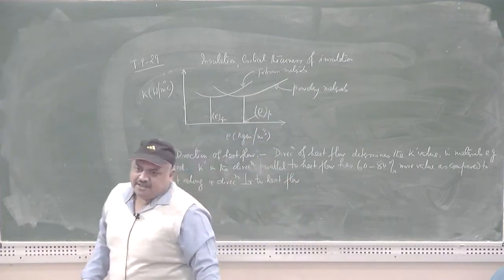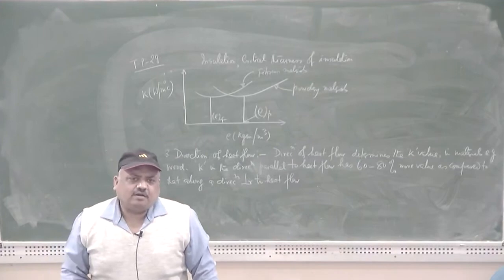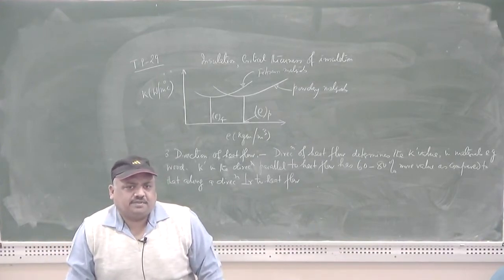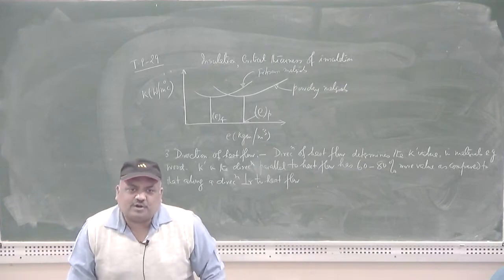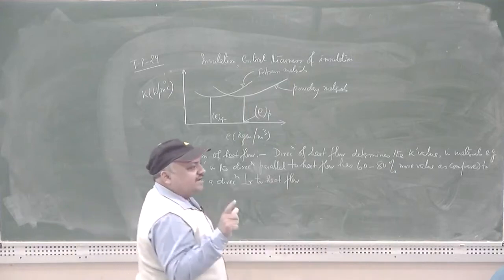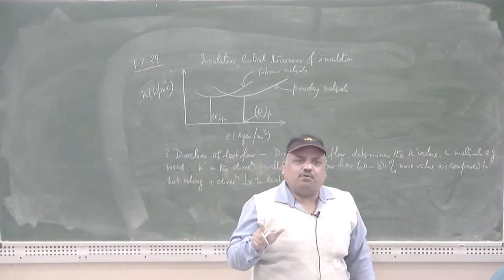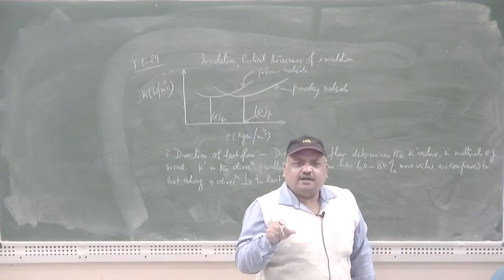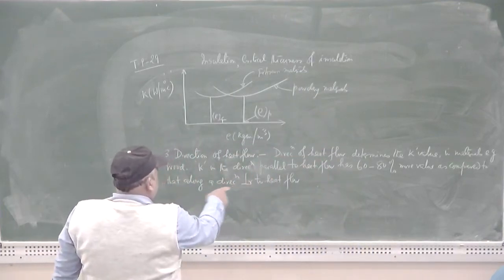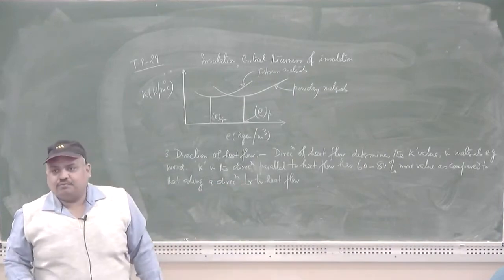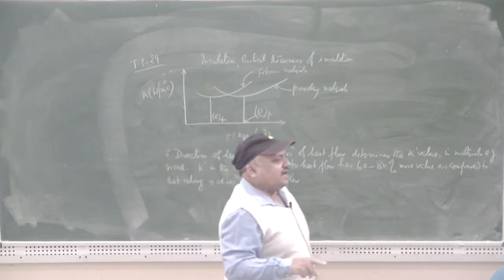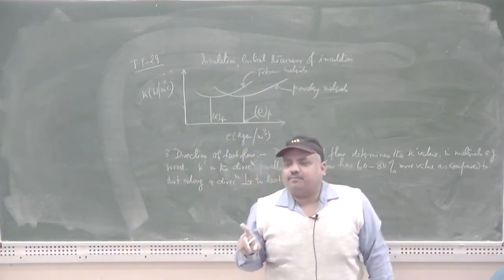You may ask me what is the important thing that can be concluded from here? The important thing which can be concluded is that whenever and wherever you have to design a fire resistant board from wood, it is necessary to keep the fiber direction perpendicular to heat flow. This is one of the most important design factors so far as the design of fire boards is concerned.